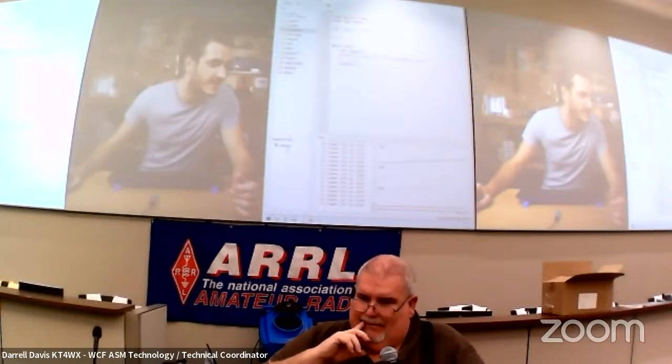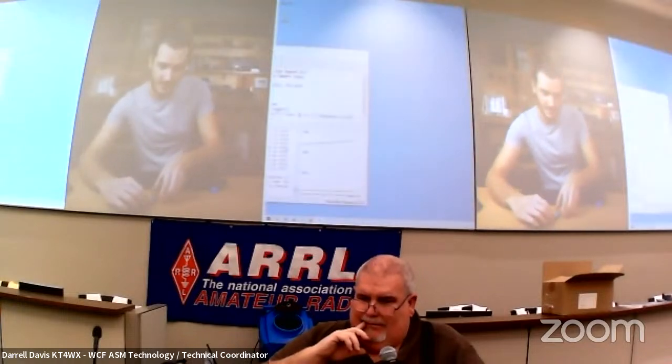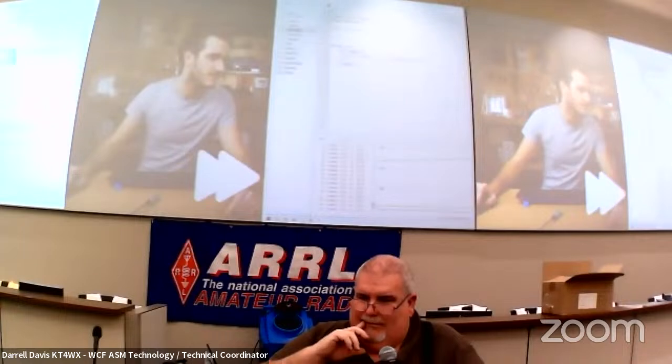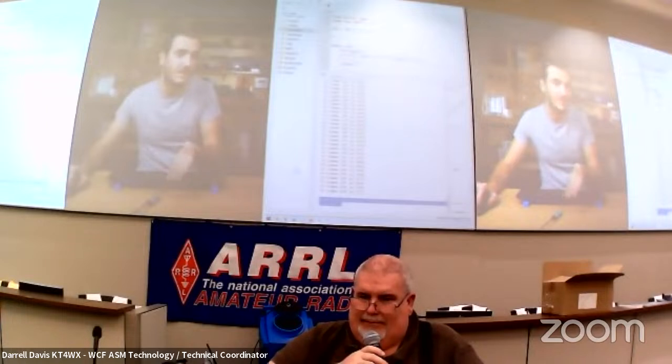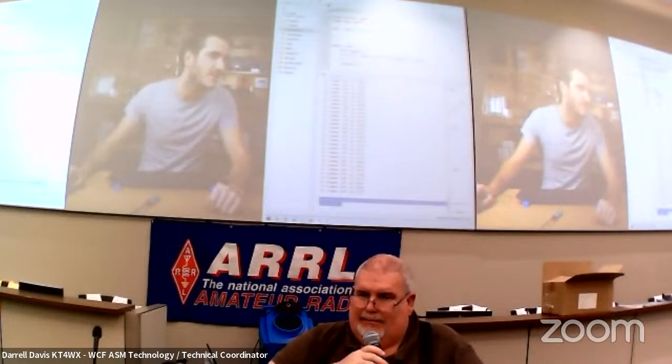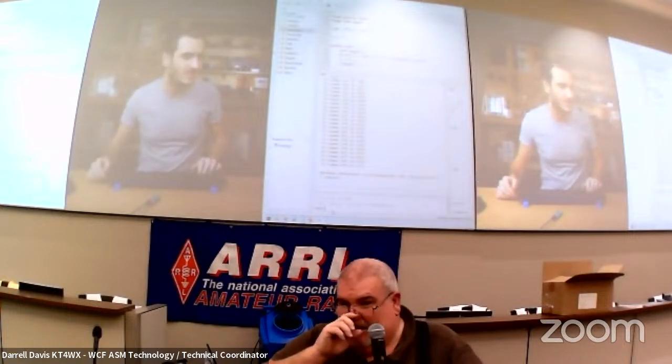Looking back at our file tree, we can see that main.py is on the Pico. So if we disconnect the Pico and then reconnect it, we can see that back in Thonny, the Pico was disconnected, and also that file tree window has disappeared. Even though our Pico was running our script, to have it appear back in Thonny, we just need to use the stop restart function. And now we have our REPL again, and we can see our file tree. However, this doesn't mean that our Pico has stopped executing its code. But we can just start it again using Control D.